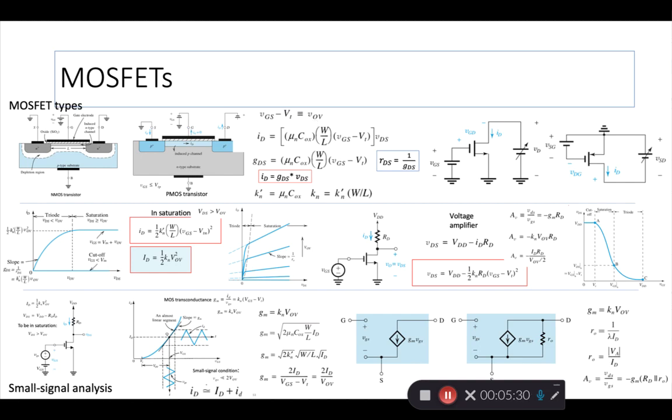Another value that is important to understand is what's called the overdrive voltage, VOV. The VOV is whatever gate to source voltage you apply here to create the capacitance, minus the threshold voltage VT, which gives you the overdrive voltage. One other important factor to remember is cutoff. In NMOS, cutoff means that the VGS is less than VT, right? If that condition exists, then there is not enough forward bias or forward voltage on the gate to even begin the process of creating a channel and creating a depletion zone and all that. So cutoff means VGS less than VT.